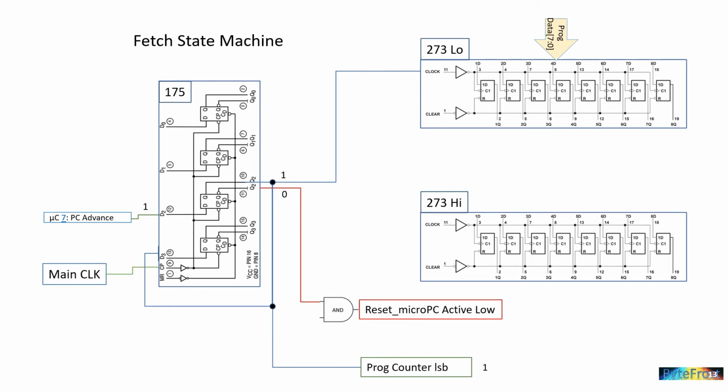Finally, we also send the output of flip-flop 2 to the decimal point LED of a program counter display. This is more of a useful debug indicator during single step. When the decimal point LED lights up, we know that we're in the middle of a fetch operation, and so that we haven't yet started to execute the instruction pointed to by the program counter.